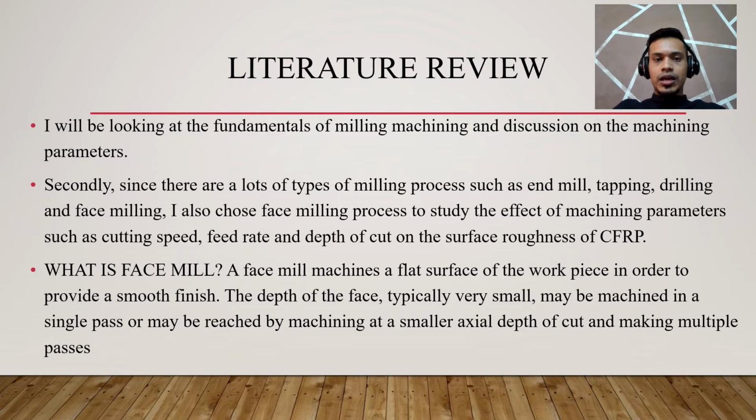Not only that, after going through all these journals, I also got to know what face milling is all about, where a face mill machines a flat surface of the workpiece in order to provide a smooth finish. The depth of the face, typically very small, may be machined in a single pass or may be reached by machining at a smaller actual depth of cut.